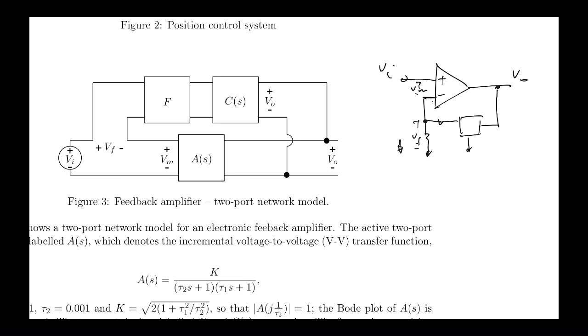But they are designed in such a way that they actually have 2 poles positioned very carefully, so that you can wrap resistor divider networks around them and always end up with a closed loop that's stable. All right? So a model for the relationship between the voltage across the input terminals of the op amp and the output, everything referenced to ground, will be a transfer function that looks like this.